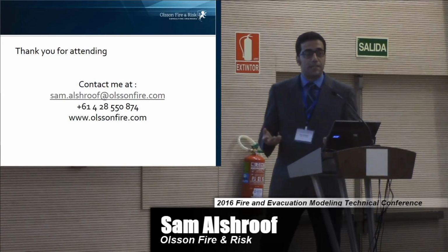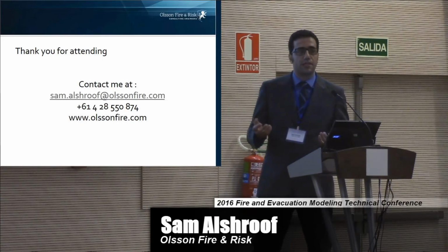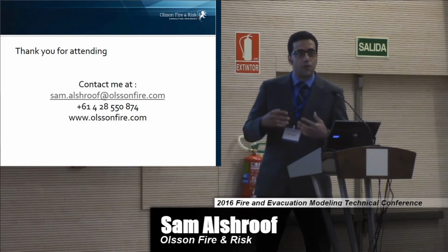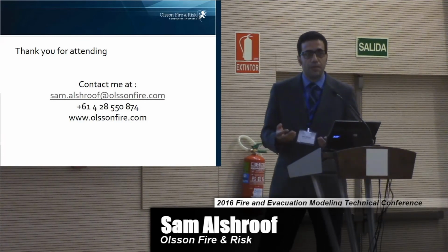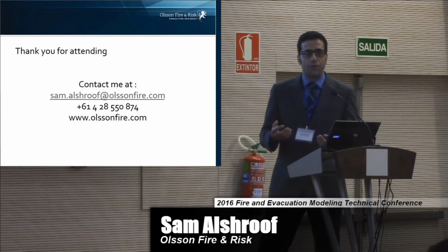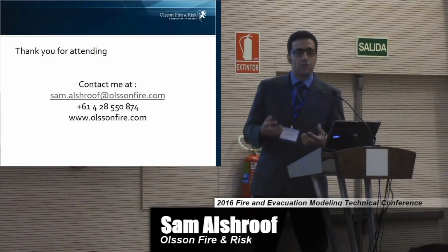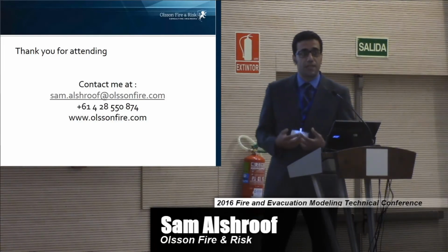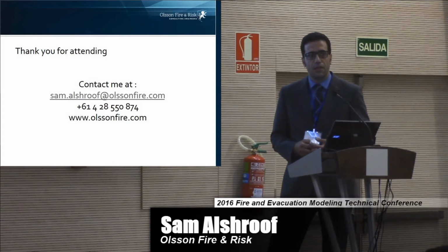So if you want to compromise that, again, I just demonstrated that you can compromise it by having maybe 2 cells. But again, you reach a point that you start coarsening your mesh and you're solving a totally different problem by coarsening the mesh. So it's a judgment of where to stop, where to refine the mesh, and how suitable your mesh is for your problem. It's a question mark we have to ask ourselves every time we run any numerical model.